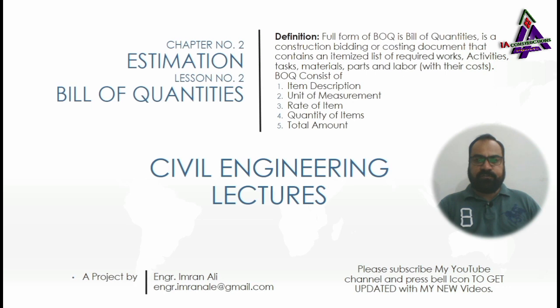BOQ consists of 5 main columns. The first column after the serial number is item description. In this column, complete detail of any activity is mentioned. For example, supply and installation of any product or material according to drawing and specifications from the approved source.